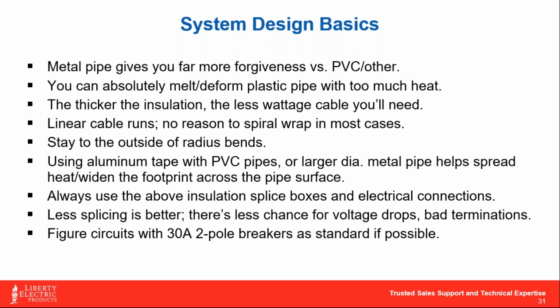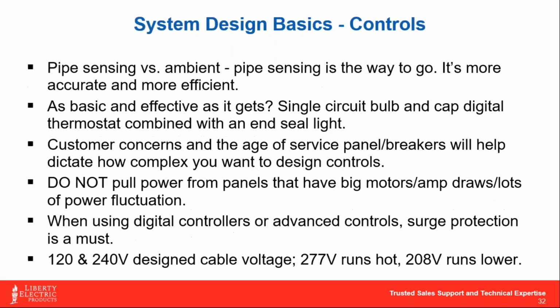So, when we talk about sizing our circuits, 30 amp 2-pole is typically the way we go. But again, it's a function of the math. If you don't have 30 amp 2-pole breakers in the facility you're designing for, then we have to work within the confines of a 20 amp or whatever we're given.